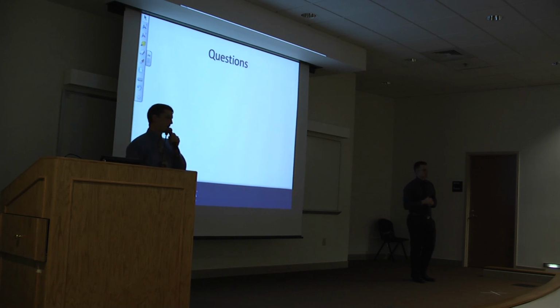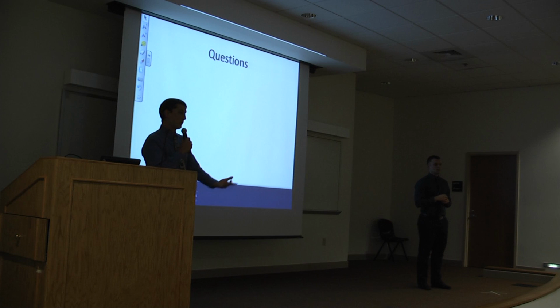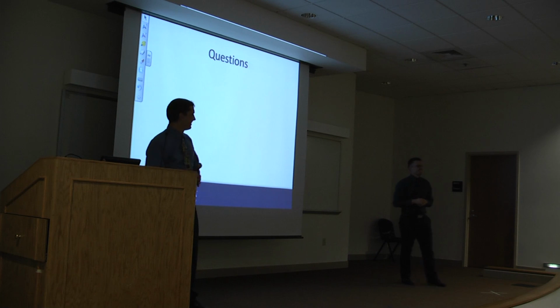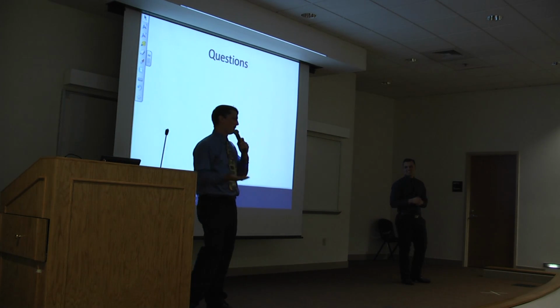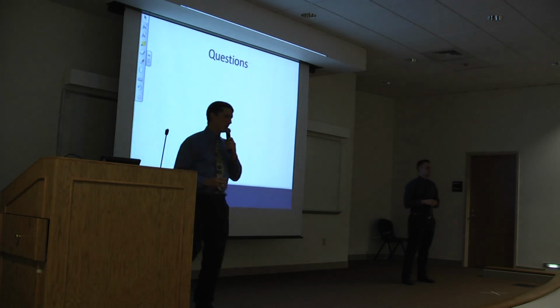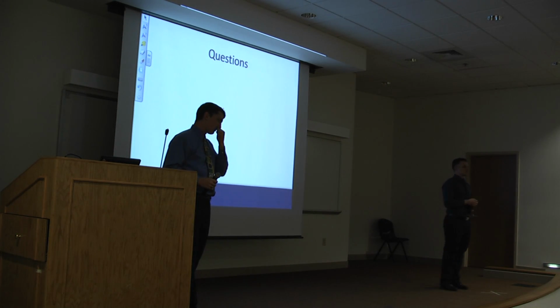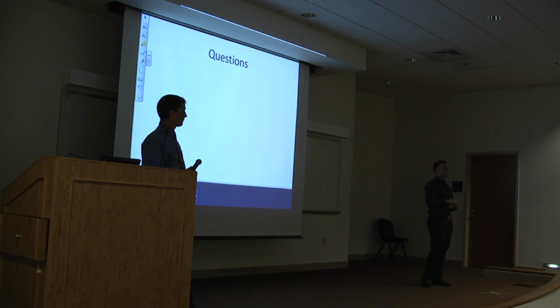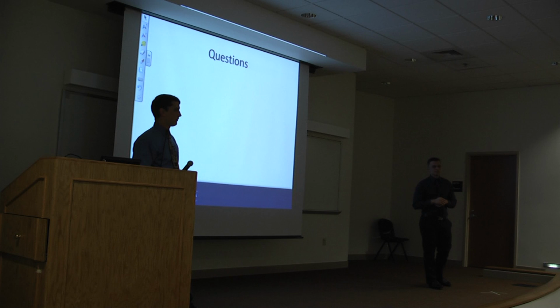Dr. Field, I actually had that same question, because then I was going to ask, did you have to give any thought to aeration of the detention basin, like a fountain, to keep it from going stagnant? That's a good question, Paul. I'll let Paul take this one. I don't think we went over the aeration of the detention basin. When it's wet, it won't be deep enough, I don't think, for a fountain running. We're looking at 3 foot. When it's full, it's 3 feet, and it'll be draining. Other questions?